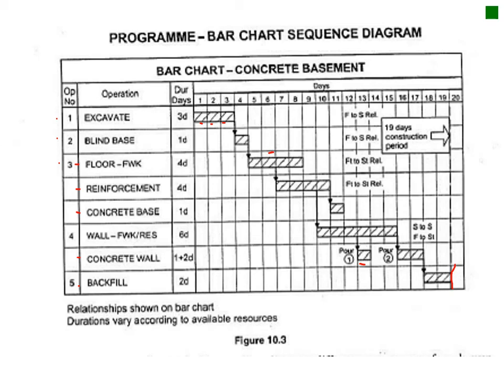So here what they've done is they've started with the placing of the formwork as the one wall is completed, and then as the other walls are being completed, the rest of the reinforcement is placed. Then the concrete is poured. You can even bring this forward if you want to. As the one wall is complete, you can maybe pour that one wall if there's a construction joint that you might have to put in between the different sides of the walls. So very simple explanation of how the sequencing works.